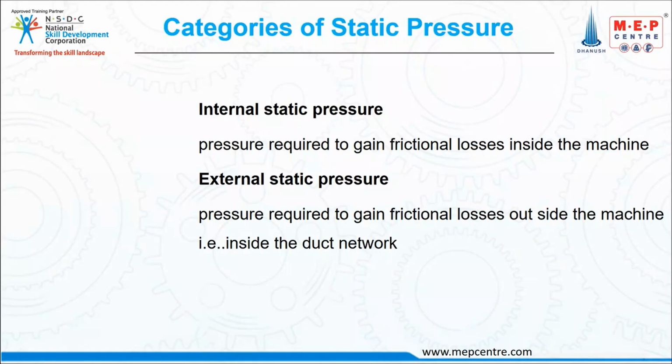Internal static pressure we won't calculate, because it is calculated by the manufacturer who designs the machine. We are designing the duct, so we calculate the external static pressure.